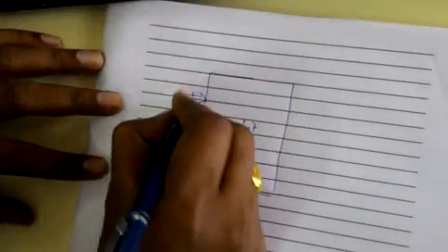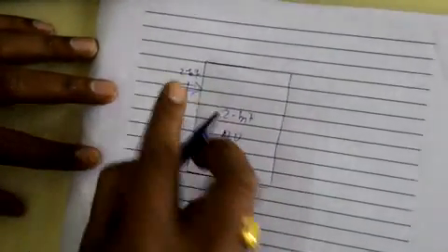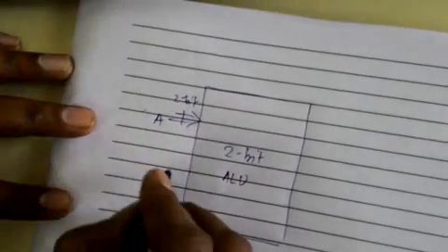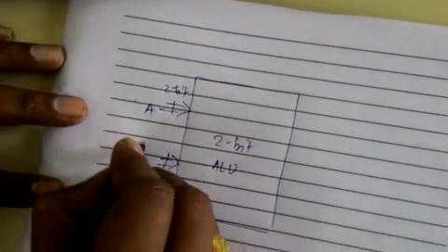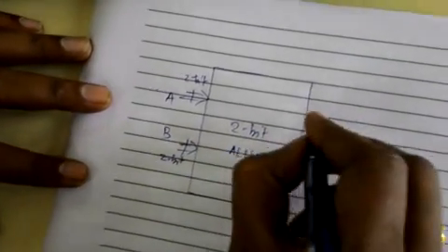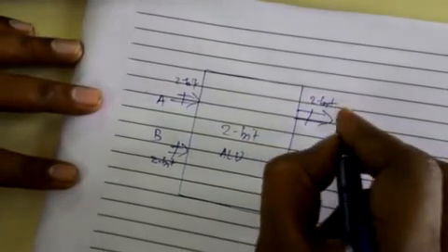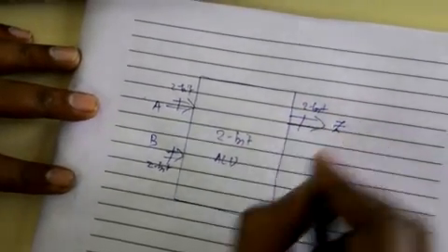So here we will need two 2-bit wide inputs. One is A, which is A(1 down to 0), being 2-bit. Another is B, which is again 2-bit wide. And to get the output, I have again a 2-bit output, which I had defined here as Z.